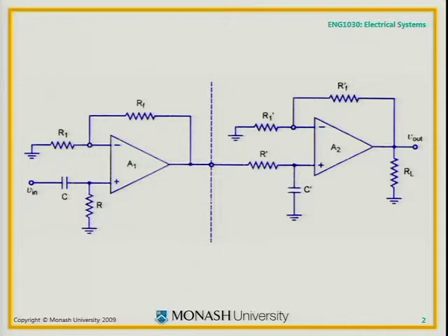Capacitors and inductors will give us something that resistors don't give us. Otherwise, we wouldn't need them. What they both give us is frequency-dependent behaviour. A behaviour that somehow changes with the input frequency. So if I have a fast sinusoid input, say at 10 megahertz versus 100 kilohertz sinusoid, the circuit will behave very differently.